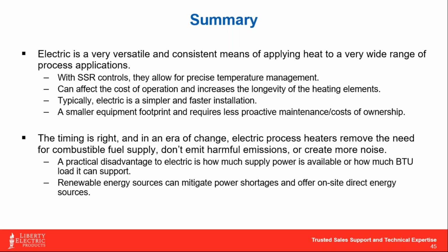And one thing I'll add with that as well is that utility companies really just have to get the power to your building. They don't have to guarantee what quality that power is when it's coming in. So integrating surge controls and power quality, power conditioning equipment, protects your investment for the long run. It's also going to ensure that your process runs a whole lot smoother and that you're much more consistent in your power delivery to your equipment. I think it's product that works in conjunction with these process heaters and pays big dividends in the long run.